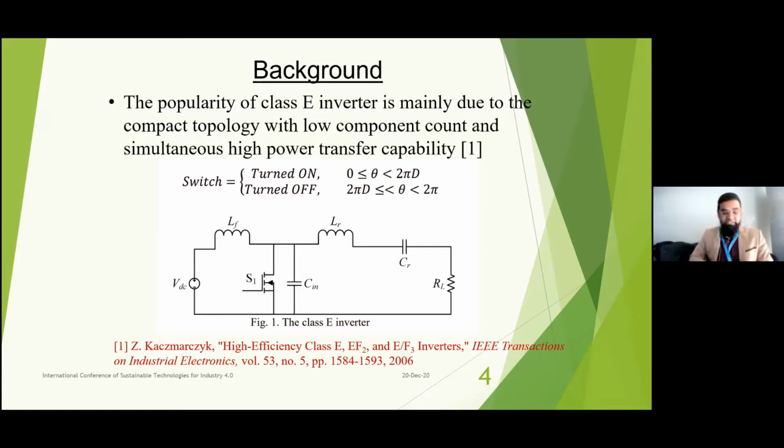So the circuit has basically 2 parts. On the left, as you can see, the input inductor, which we call the DC input feed inductor. And there is a lot of literature on how we design an input feed inductor. Basically, we can make it a very high value to ensure that input current is a DC with low input ripple current, or we can include this input DC feed inductor and combine it with the resonance circuit to operate in the resonance operation.